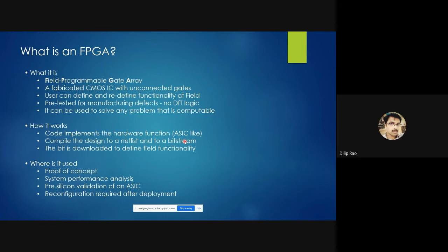It's the equivalent of a GDS. I don't know if you have heard of this term, GDS, the geometric data stream. What GDS is to an ASIC, this bitstream is to an FPGA. It's going to define the functionality. Fuses are an outdated technology, but later we have SRAM-based FPGAs. This bitstream defines what parts are programmed in what way, what switches are on, what switches are off, what functionality is programmed into a LUT, what registers are being used, what the multiplexer selection lines are, and in essence what circuit is built into the device.